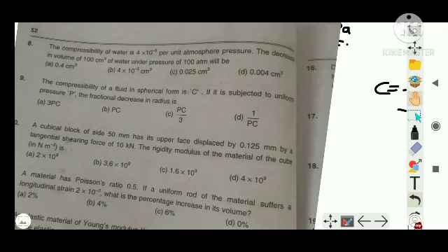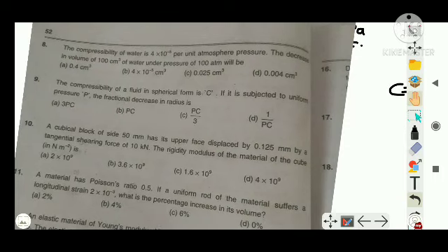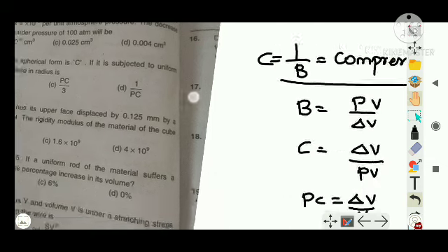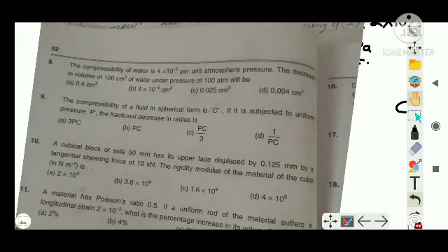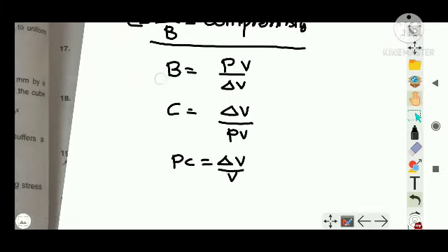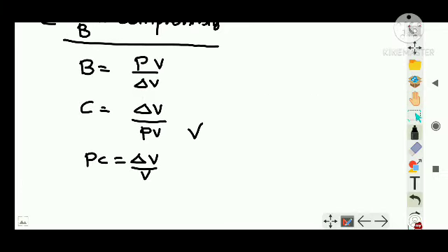you are given the compressibility of water is 4 into 10 to the power minus 5. Okay, this is something I've given from my side. Write it down. We have not moved to the question till now. You are given the compressibility of water as 4 into 10 to the power minus 5 unit, right? C is given and the decrease in volume is asked. You are asked delta V. You are given the initial volume, that is 100 centimeter cube of water, and you give a P of 100 atmosphere. Then what is the change in volume, right? So you have written down this much equation, I believe.